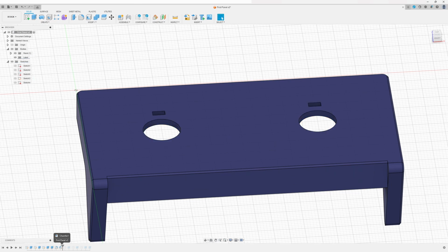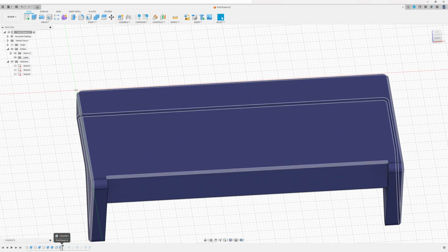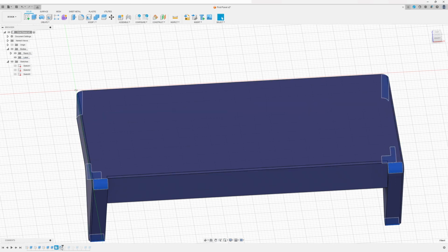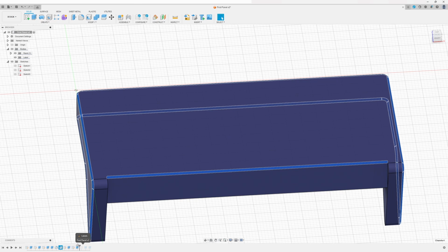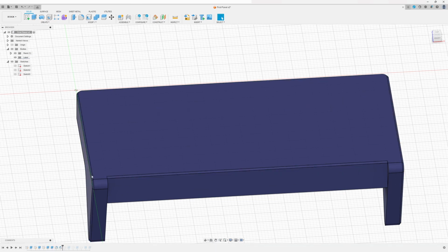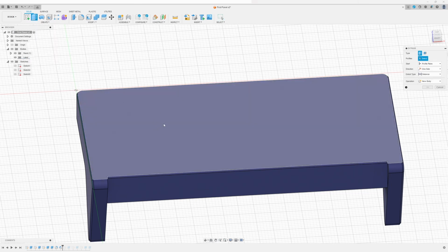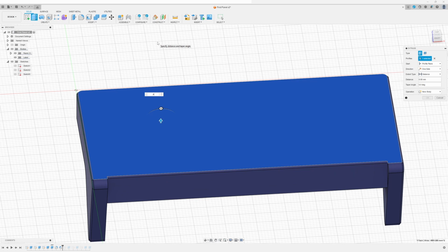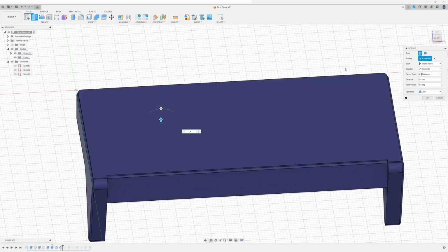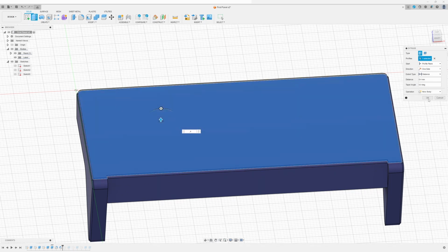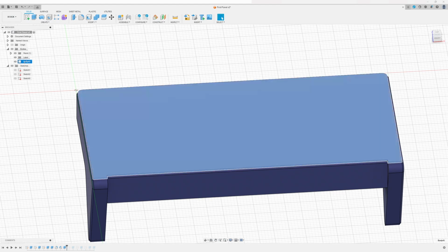And if I'm moving back the marker, now you can see the fillets and the chamfers are created before these cutouts are created. And jump back after the fillet operation, and now we will add another extrusion to it. So go to the extrusion tool, select the upper face, and create an extrusion upwards 0.4 millimeters, and make sure that the operation type is set to new body. So this body is our transparent layer.